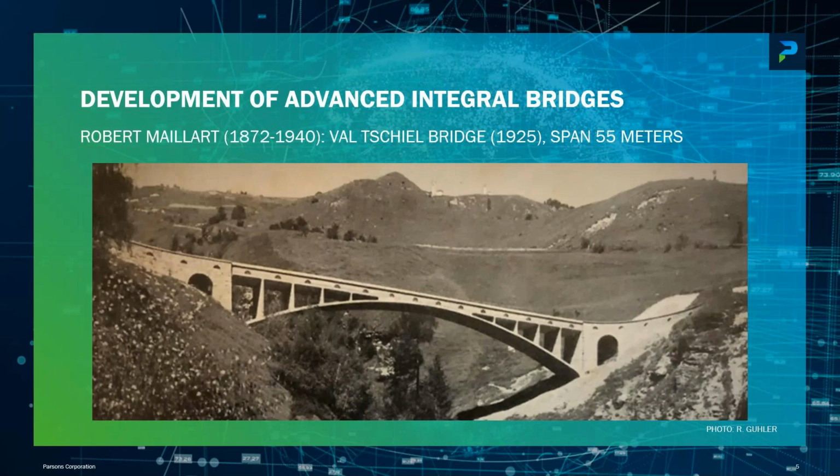This bridge is a deck-stiffened arch, so a very, very slender arch bridge where you have slender walls that support a superstructure. And the arch alone couldn't survive unsymmetrically distributed live loads. You need a stiffening girder, and this stiffening girder is here provided by the barriers. So Robert Maillart knew how to use the material and to look for synergy effects in the barrier that he needs anyway. He used this as a structural element to stiffen the arch.